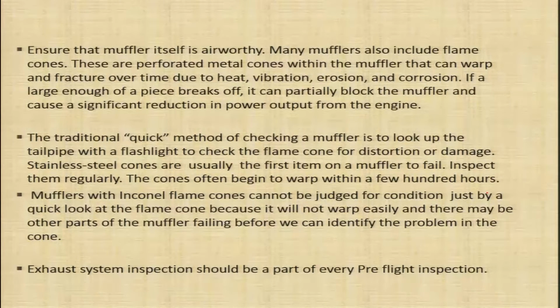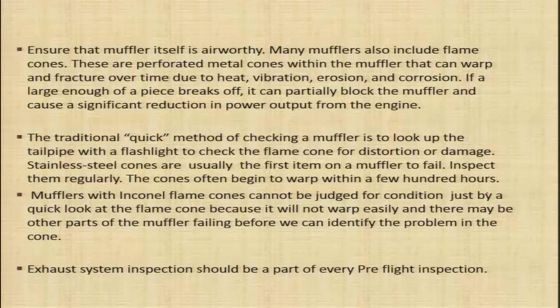leakage. We need to inspect the exhaust system as per the manufacturer's recommendation at proper intervals as per the guidelines of the manufacturer, and in fact in every pre-flight inspection the exhaust system should be carefully inspected. So this was all about the exhaust system. We will look at various exhaust systems on various aircraft.